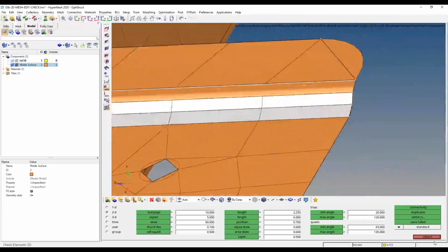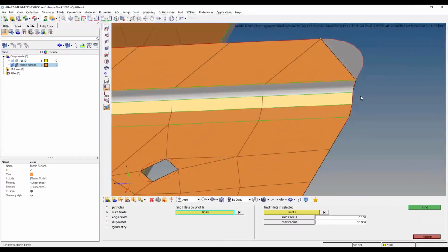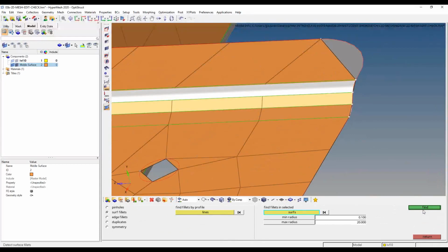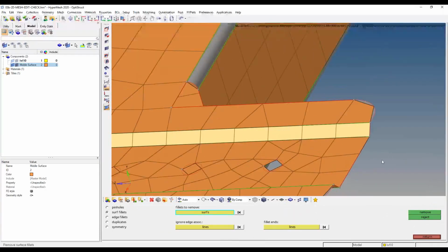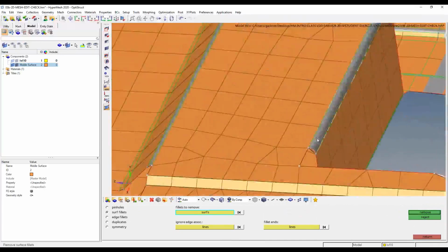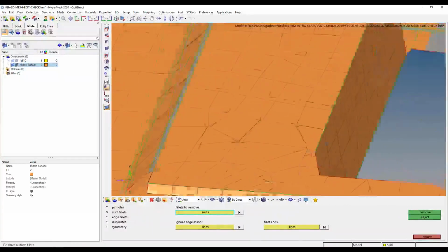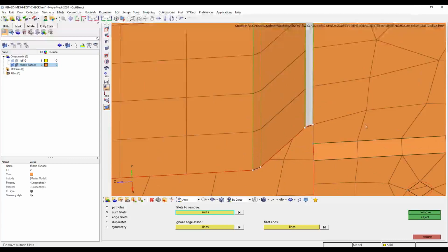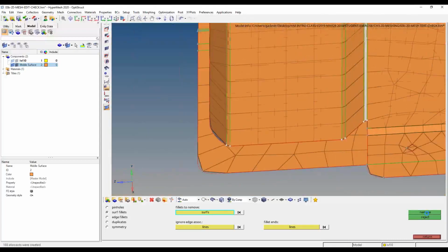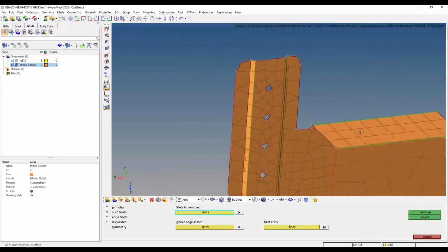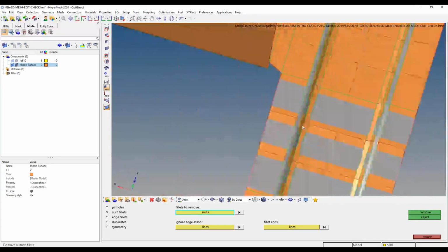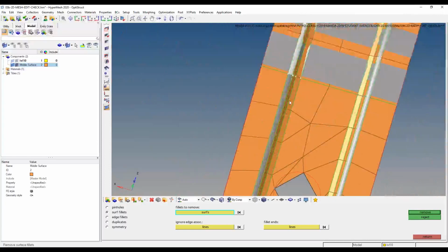So maybe I would do a similar thing to defeature out that fillet on the other side. And that'd actually be preferable, so that we're doing this in a uniform way, where we're not just removing some fillets and keeping some. We want to be pretty smart about being consistent about removing these fillets. So I'm actually going to come in this part here, and I've seen this plenty of times. I'm just going to remove a lot of these surface fillets to make this thing a lot more simple to mesh.